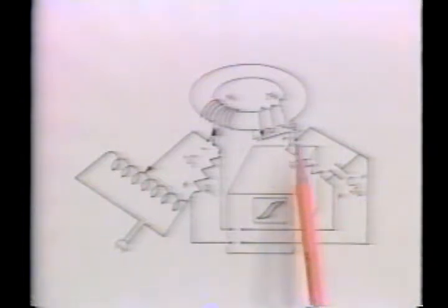With the capacitor essentially a short circuit, the current is approximately V2 over R2. From Faraday's law, the terminal voltage of the sensing coil is the time rate of change of the magnetic flux linking the coil. This current then charges the capacitor. By comparing these last two equations, we can see that the voltage across the capacitor is proportional to the magnetic flux linking the sensing coil.